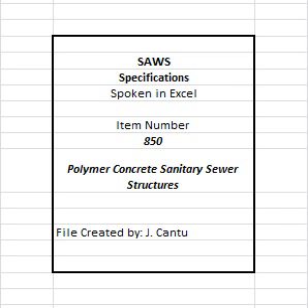7. Submit manufacturer's certification for each type of cast iron frame, grate, cover, or hatch. 8. Materials to be used in fabricating pipe drop connections must be approved by Director of Engineering. 9. Materials to be used for pipe connections. 10. Materials to be used for stubs and stub plugs, if required. 11. Proof of independent chemical resistance testing conducted in accordance with the standard specifications. 12. Current ISO 9001 certification or SAWS approved certification. 13. Submit proposed methods, equipment, materials, and sequence of operations for sewer construction. 14. Submit all test reports and pre- and post-sewer television inspection video. 15. Videos become property of SAWS.